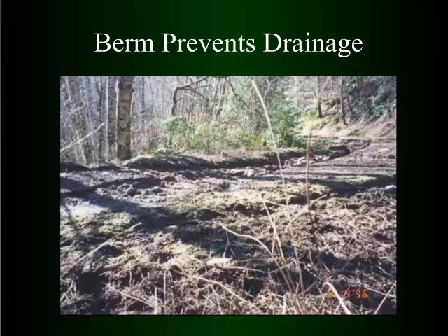Berms, you see a lot on the outside, and they can really cause problems. There are situations I've seen where a road will go for a half mile with a berm and just keep accumulating water until finally it gets enough velocity to blow its way through the berm, and by then it may have cut down along the edge of your road several feet. This one here, you can see that there's quite a bit of cutting here, and it's mainly because the natural flow across and down the hill is being impeded by the berm there.